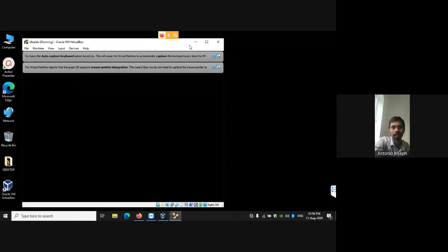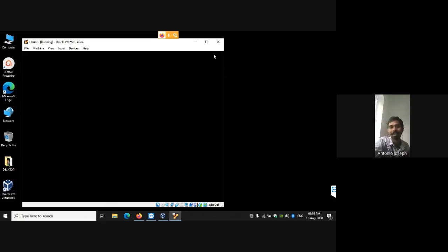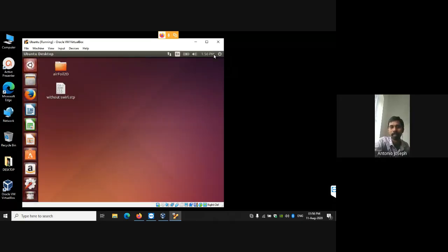Then again, you want to export that. In Salome, you want to export all the surfaces and then group them according to our patch names, and then export that in STL format. Then again, combine all those files into a single file as we did in the case of PipeFlow, and then save the tri surface.